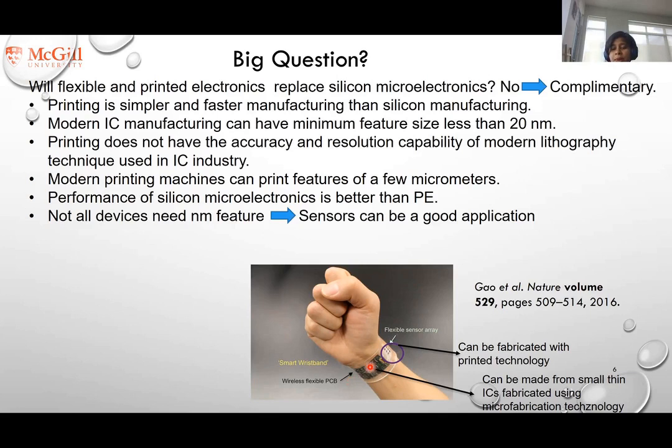Whereas the rest of the part, which has the analog front end, controlling unit, and wireless communication unit, this part is difficult because we need high speed transistors and we still need to be compact. So the rest of this electronics part is difficult to make with printed electronics.